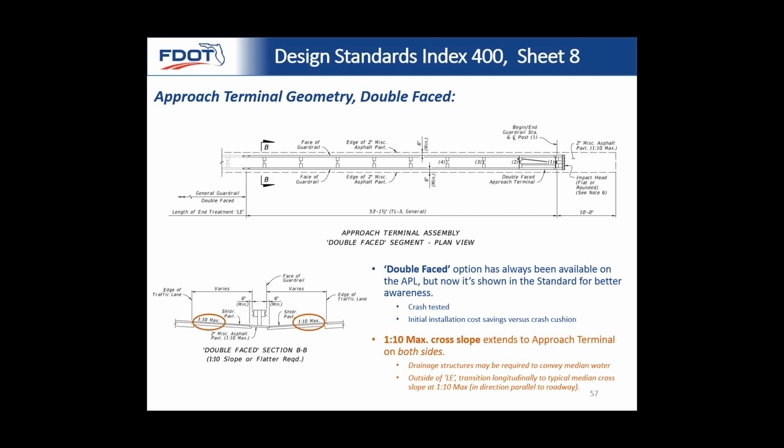That's a case where you might want to consider crash cushion because they have lower cost of maintenance. You don't have to replace the entire system. If this gets hit, you generally replace the entire system. If a crash cushion gets hit, they all brag over how much it costs for them to do repair work and reset it to the point where it's good again for another use. And so they're initially more expensive, but then their maintenance is lower cost. Here, you have initially lower cost, but then you have to replace the whole thing if it's hit. So you really want to use this when it's truly on the roadside and you don't have vehicles directed straight at it, and you expect it to be hit a lot less. But you could save a lot of money just by using this as a default option.